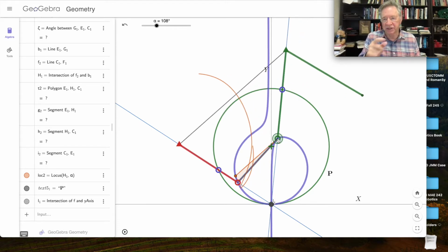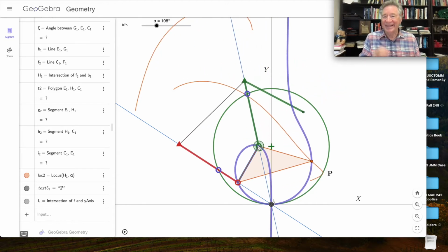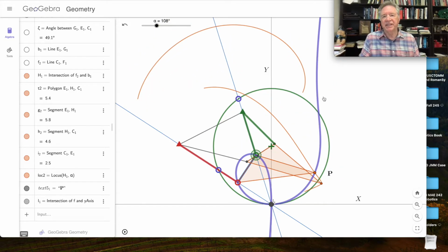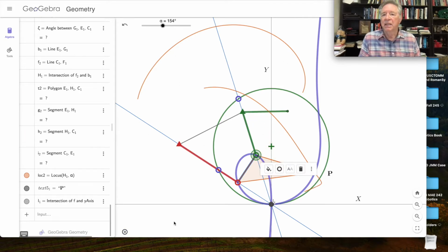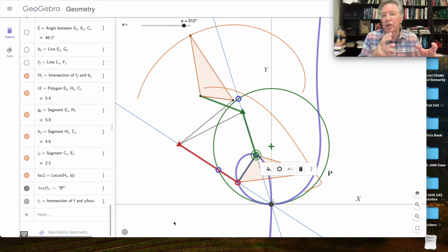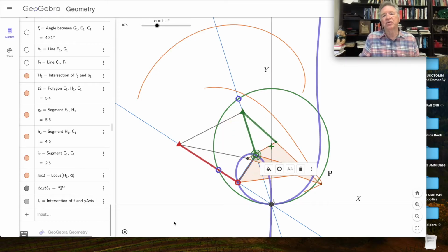It's a construction using the pole, which is the origin of the canonical frame, the intersection with the inflection circle, and the actual pivot to calculate where the center of curvature is. Now you're seeing the trajectory of the coupler point curve, and it is broken because the linkage itself can't move continuously through all of the positions.